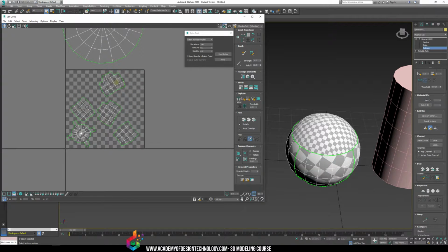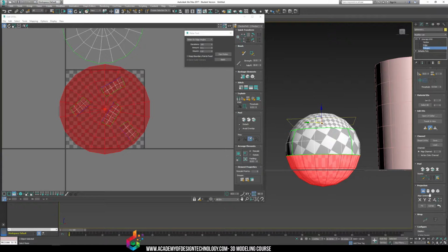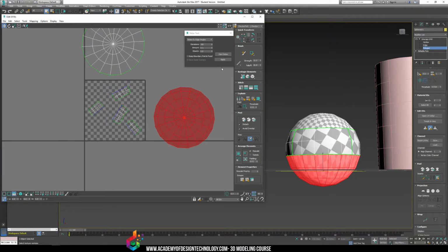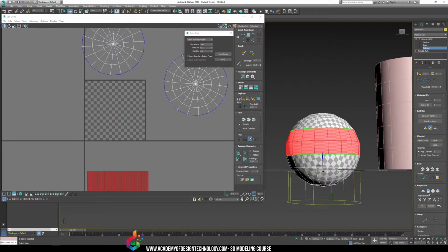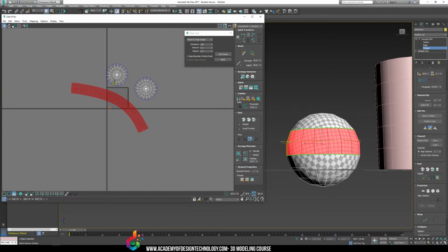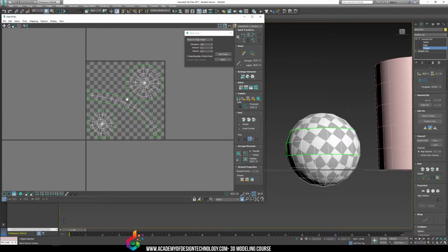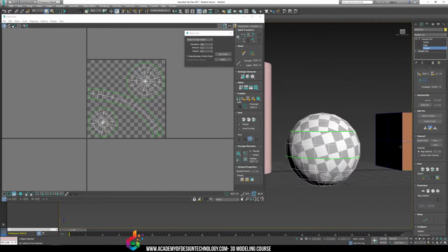See, we have this, and then maybe the bottom part of the sphere here, same thing, best fit, relax it a bit like that. Then grab the entire middle, and I'm going to use a cylinder for this part. Best alignment for the cylinder, start relaxing it. And now I'm going to pack all my elements. I'm going to rescale them first. So rescale elements. I always rescale elements because that's the size they need to be. And then I pack them together. And boom. There you go.